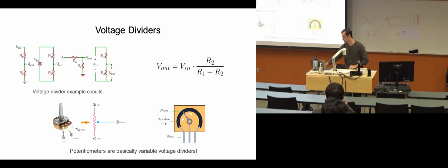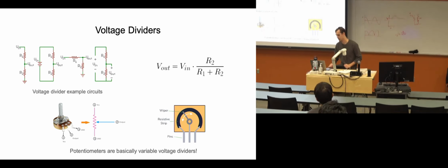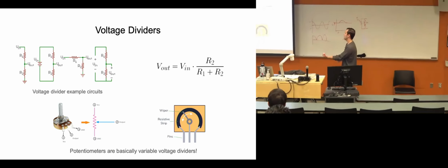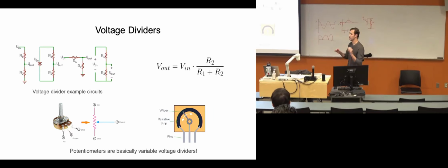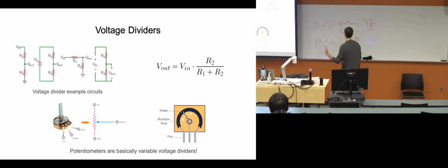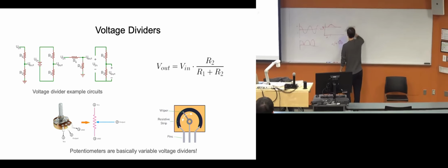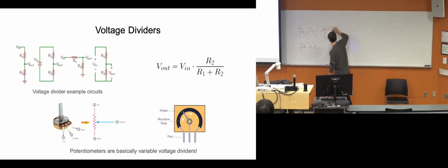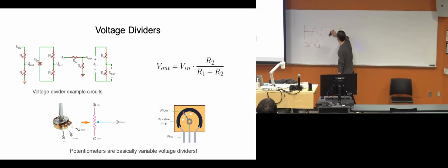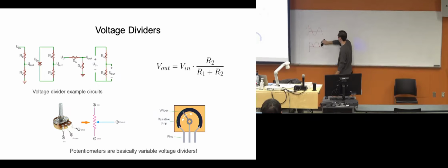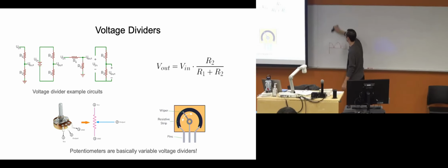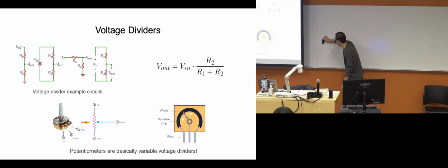All right, we're going to talk about voltage dividers. This is going to be super important for lab 5, I believe is ADCs. It's either lab 5 or lab 6, ADCs and DACs. This is basically a way to take any voltage and get it to the voltage you need, right? It might not be super power efficient. That's a whole other problem. But basically, it's just using the resistors we talked about to make a divider. So it's just 2 resistors over voltage, and then you should be able to get any voltage between your high voltage and 0 volts, obviously.